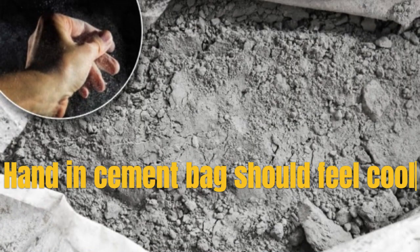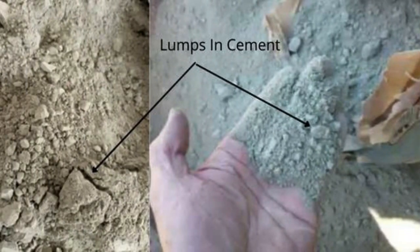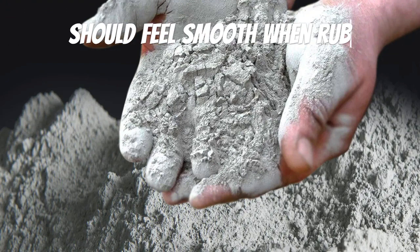Temperature. When you put your hand in a cement bag, it should feel cool. Lumps. In cement, lumps are formed due to absorption of moisture. Good cement has no lumps. Fineness. When we rub the cement between our fingers, it should feel smooth and not rough.